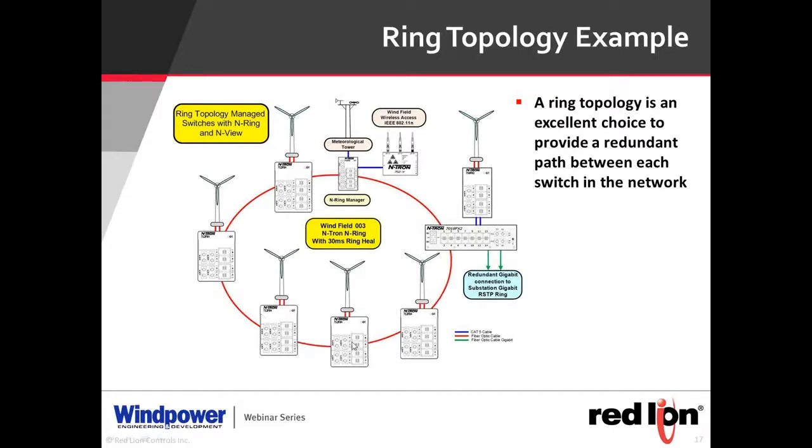By simply installing a ring, the ring manager will block one communication port, and the data will then go around to these other devices. The manager will send a health check packet to make sure that the ring is intact, and upon detecting a break, it will heal the segment that was originally broken and can change the path. So data is ensured to continue to flow along.